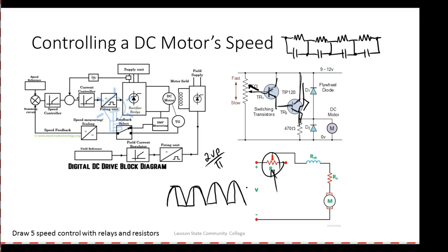So what does closed-loop mean? We get feedback. So I'd set the motor. I say I want the motor to run at 200 RPM, and by George, they would adjust the firing angle of the SCR to average out, so the motor would run what? 200. If it tried to slow down, it would do what? It would increase the voltage automatically. If it tried to speed up, it would decrease it.